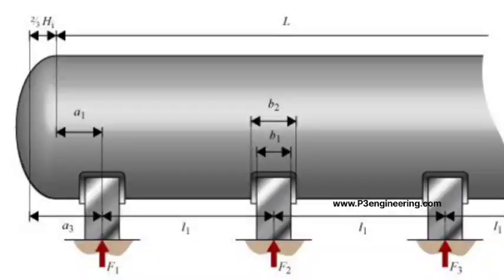So your query is where the placement of this third saddle and how it is to be located, right? Yes. Okay, Ramakrishna or Mali, you want to answer? I think in PVElite we can add multiple saddles. Yes, in PVElite it can be added, but in many reference books I have seen that the placement of the third saddle becomes a big problem because the load may not be equally distributed.